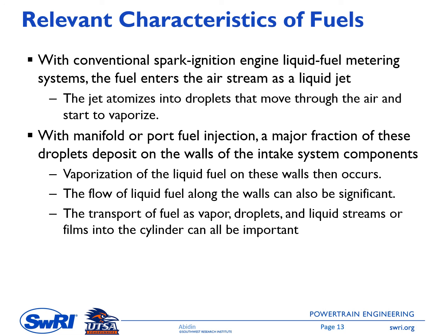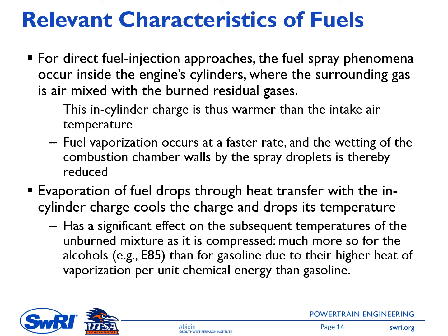For the direct fuel injection approach, the fuel spray phenomena occur inside the cylinder of the engine, and the surrounding of this fuel spray is the charged air and the residual gas. The residual gas is hot, and therefore the environment for direct fuel injection is hotter, and thus increases the evaporation rate of the fuel. The evaporation of the fuel requires energy, and this energy is taken from the charged mixture, so the mixture of air and the residual. It can also be taken from the wall heat transfer. Then the characteristics of the fuel will impact the evaporation rate of the charge.